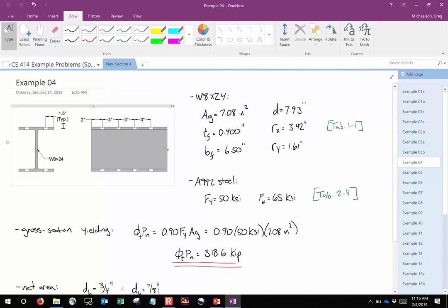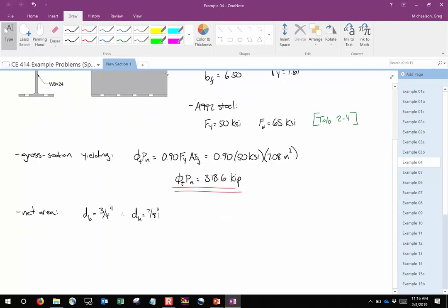4, right? Here's the cross section. Samurai sword or lightsaber. We're cutting through 1, 2, 3, 4, right? Okay. And what is the area of that hole? It's the diameter of the hole times what? The thickness of what? Do we have that value? Yeah, I had you look it up earlier. See, it's like I'm not completely crazy. So I propose then that the net area is the gross area minus 4 times the diameter of the hole times the flange thickness.